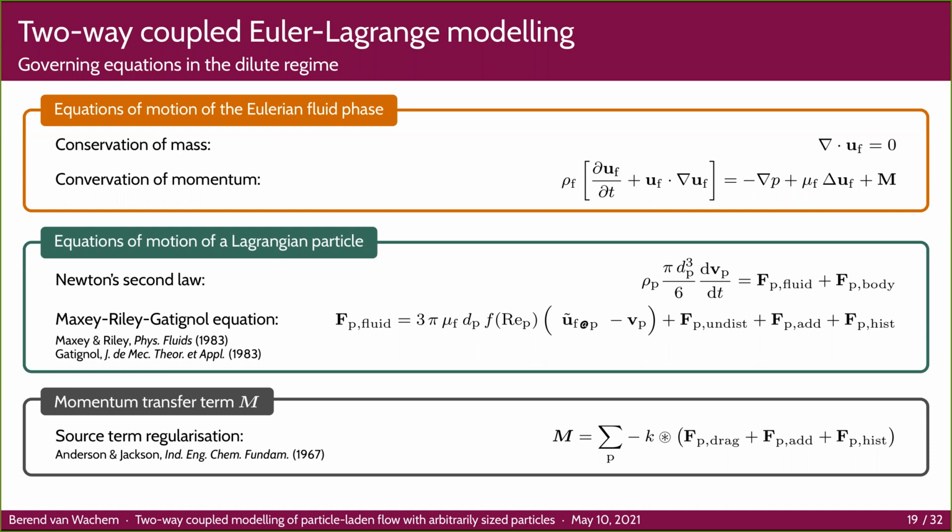Yeah, I see. So if we don't apply these corrections, we can stick to a 5 to 10 ratio, right? Well, and to my surprise, because I've been telling people for many years in the best practice guideline series courses that we give, you could do a factor 10 and then the error is very small. You can still get errors up to 10% in drag. So that's still a significant error if you take factor 10. But that's in literature always been taken to be a safe guideline, you could say, yes. Okay, thank you. You're welcome.